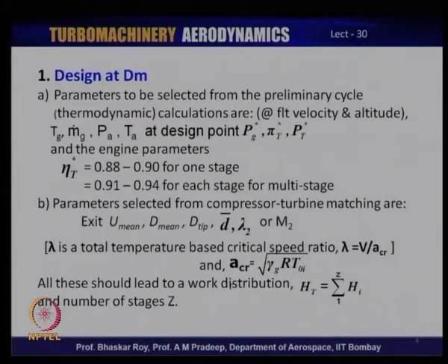It is likely to be a slightly high pressure and high pressure ratio axial flow turbine. Whereas, if you have a multi-stage turbine, the overall multi-stage efficiency would again be of the order of 90% or so, whereas the individual stage efficiencies could be higher than that, and individual stage efficiencies nowadays could indeed be as high as 94%.